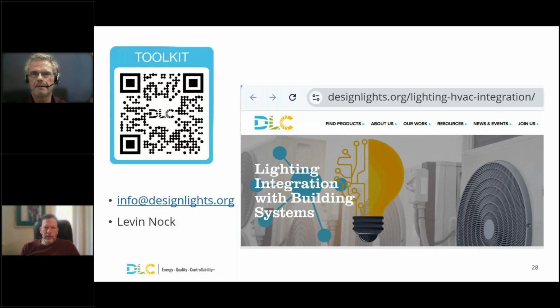Yeah, it sort of does. There's two ways, well, actually there's three ways of absorbing the lighting information into the HVAC system. One is a direct connection between the lighting occupancy sensor and the programmable controller or equipment that needs that data. It would be the same as using an outside air temperature sensor to give you that information to control your logic. You'd use the lighting occupancy sensor data over, let's say, a BACnet network directly into that controller. So it'd be a direct, what we call a peer-to-peer connection.